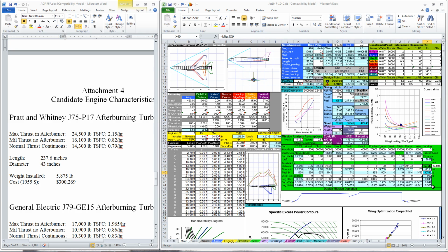And if the price of the airplanes isn't really that much different, we may want to go with the other wing that was recommended by optimization. We said that was 3.4, and 42 degrees of sweep. Saves 100 pounds of gas or something like that, but maybe when we make the airplane heavier, it won't really. Yeah, see, I don't think it's actually helping us that much.